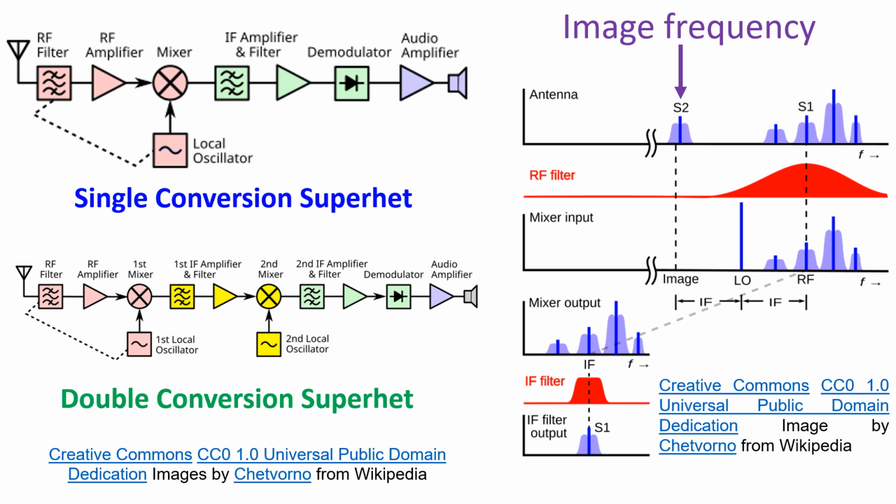Image frequency interference is prevented by using a good filter at the initial RF amplifier stage. Use of a double or triple conversion superheterodyne receiver is another option, as discussed earlier. A higher first intermediate frequency in these radios increases the spacing between the image frequency and the intended frequency. That makes filtering at the initial RF amplifier stage easier.